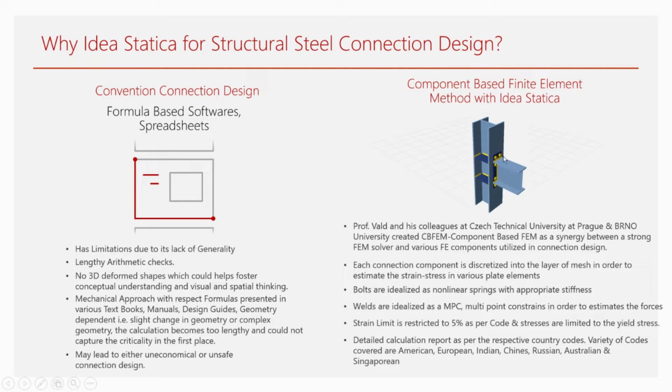The bolts are idealized as nonlinear springs with appropriate stiffness based on their diameter and stresses. Welds are idealized as multi-point constraints in order to estimate the forces in them. The strain limit is restricted to 5% as per the code requirements, and stresses are limited to the yield stress, which is user-defined. This approach has the flexibility to modify the geometry at any time. Any connection can be modeled, analyzed, and designed in this software.